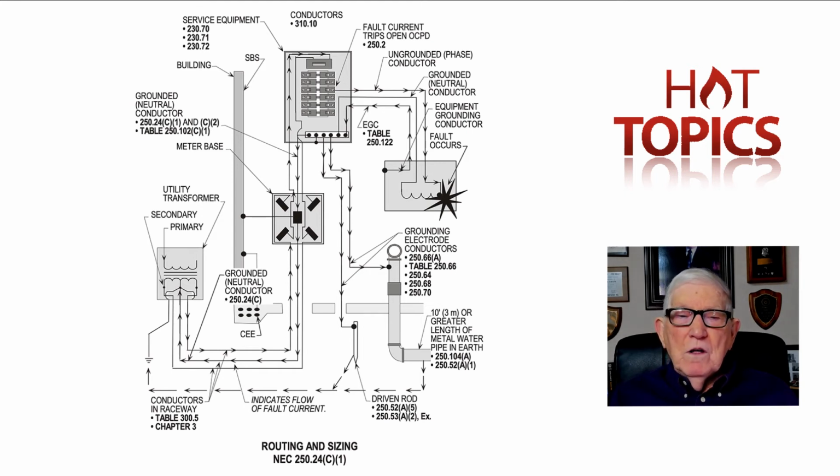Why does it become a grounded conductor then? Table 250.102(C)(1). It has nothing to do with the neutral current, because we're going to set a main and install a main and feed a transformer, 480 volt, 3-wire primary, and step it down to 120/208 maybe for our 120 volt loads, because we don't have any neutral loads at 277 at all. So keep that in mind when you're reviewing the short circuit current, the ground fault.